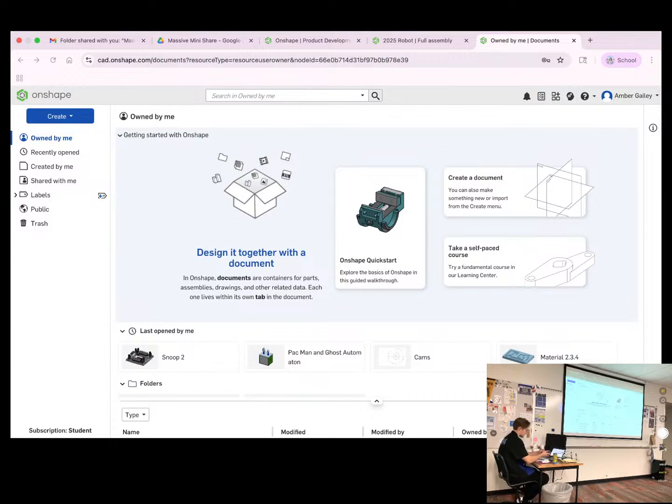Electrical. I love this picture. Andy had this. He's got a master main breaker right in the mouth of an alligator. You'd be surprised during inspections the places we find main breakers. They'll be buried down in the belly of a robot, and the team will say, well, you can reach your arm in here like this, and you can get under there, and you can turn it on and off. That's great unless your robot's malfunctioning, and somebody might get hurt trying to turn the power off to your robot, or you might even get hurt doing that.